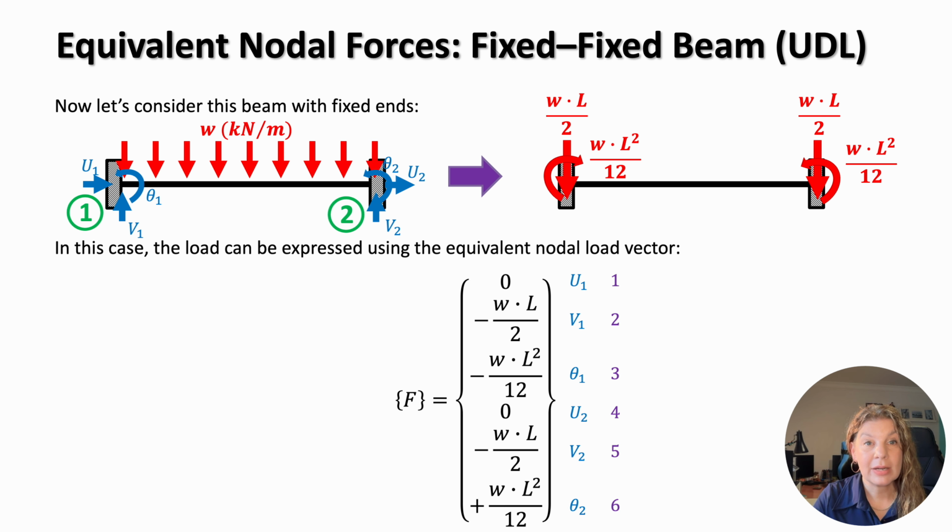The magnitudes match the standard fixed end moments for a prismatic beam under a UDL, and the opposite sign ensures overall equilibrium of end couples. The axial entries remain 0 because a vertical UDL does not generate any axial actions in this element formulation. And putting it together, the consistent load vector for the fixed case is shown here.